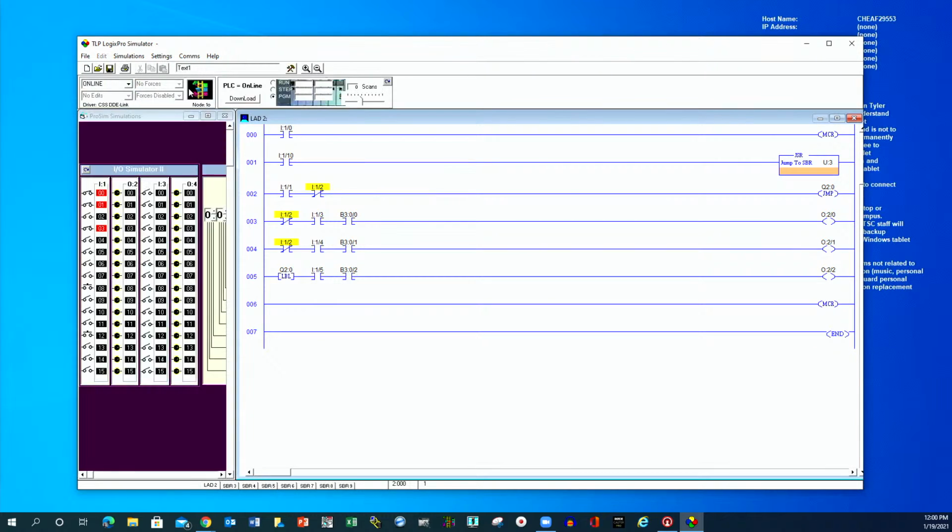All right, I'm going to go online and put my PLC in run. All right, so my MCR is now open. Let me change these all to maintained. Input 10 is going to be your MCR fence. So that fence is active. We're not going to jump yet, but we're going to say that we are jumping over this. So if I turned on any of these right now, none of these would work because I'm jumping over to this guy here.